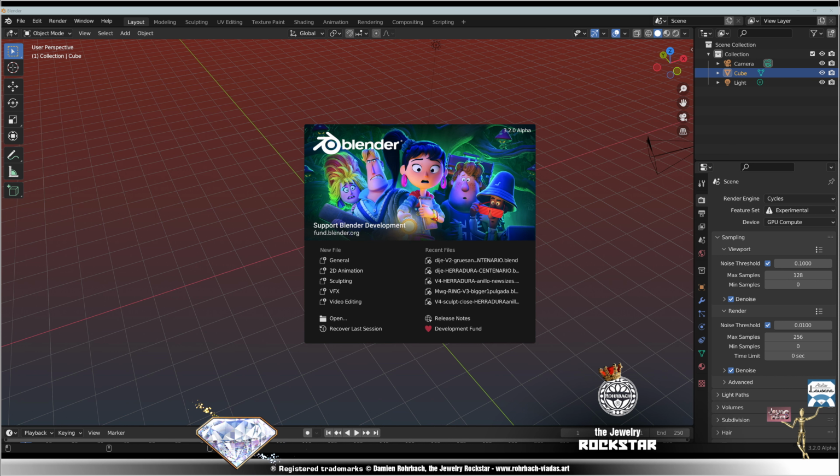Okay, I don't like the look of the shading here, so let's go to Object, Shade Flat. Looks better. And also we need to have a cut on the inside. Let's go Shift S to bring the 3D cursor right there. Add Object, Cylinder. Let's put 120 vertices. And let's adjust the scale to have a small border on the inside.